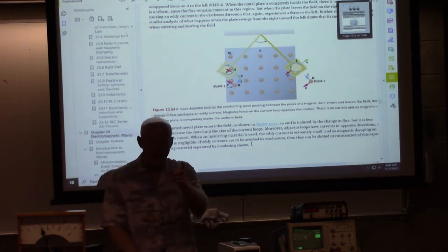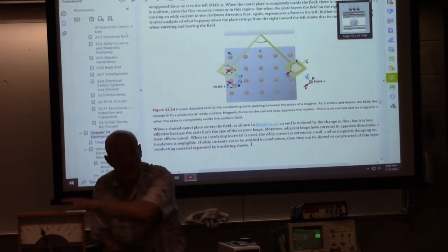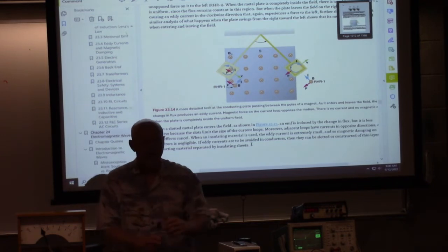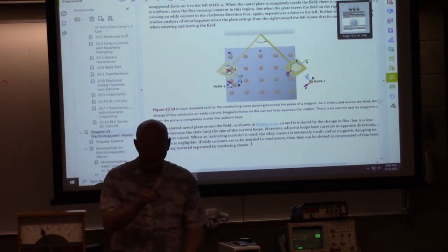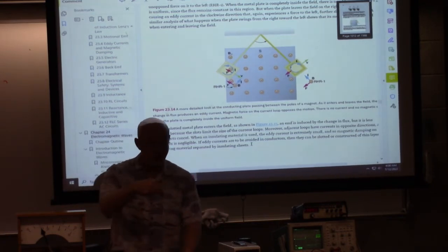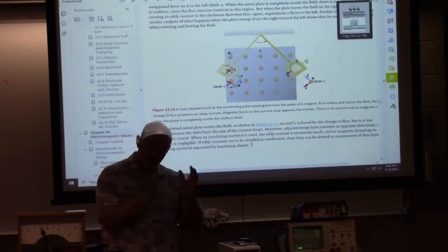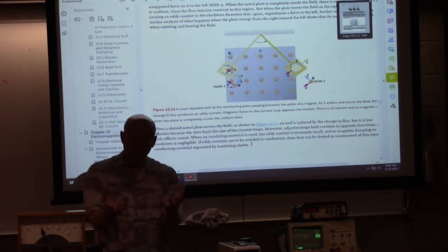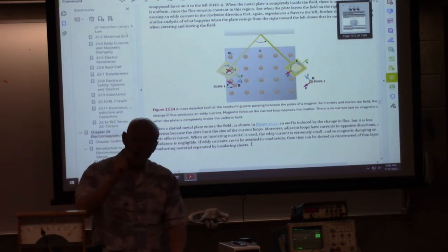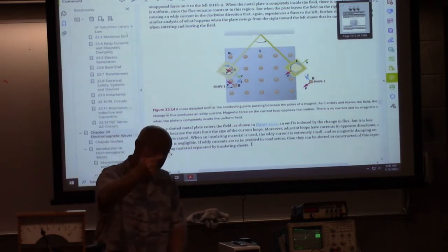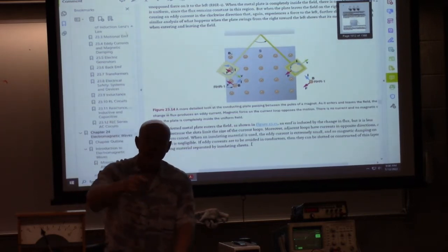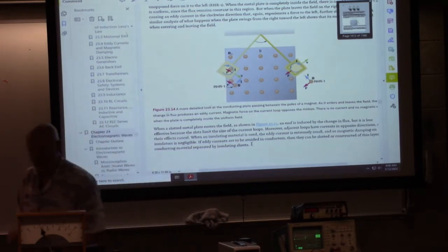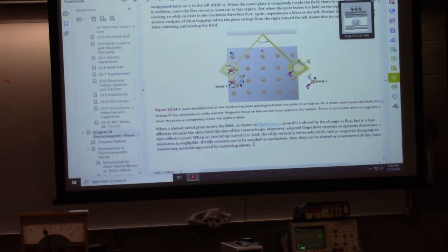So what direction does the flux need to be from the secondary? Outward, right? It opposes the change. We had 0, now we're getting a bunch inward, so it wants to make it outward, so the total is still 0. So which direction does the current have to be in the secondary in order to make the flux come out?